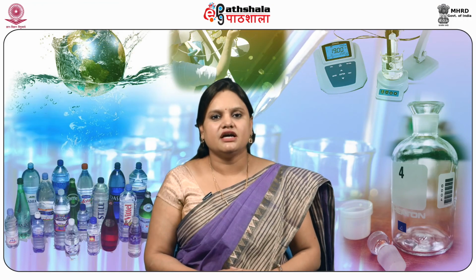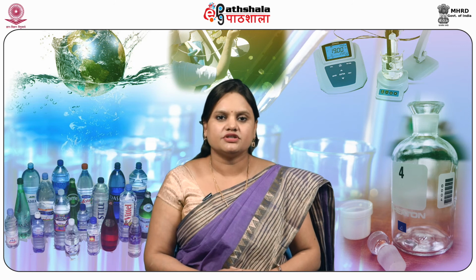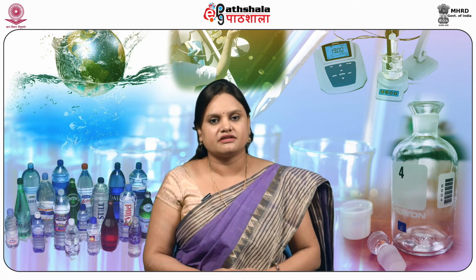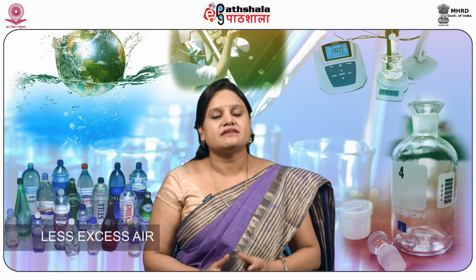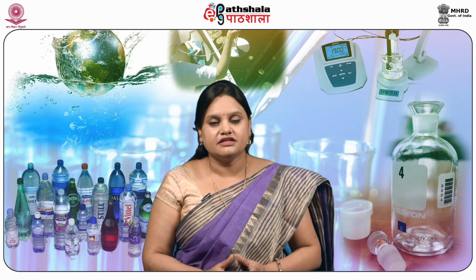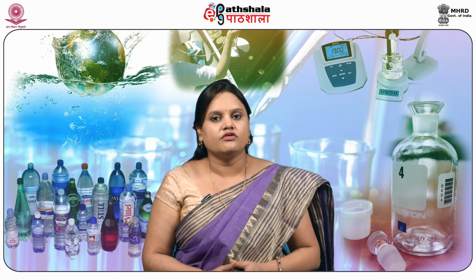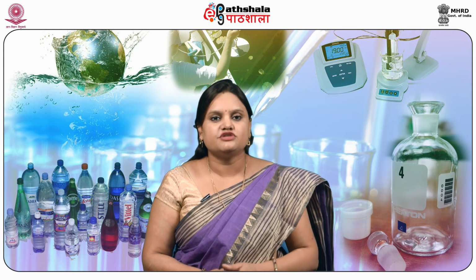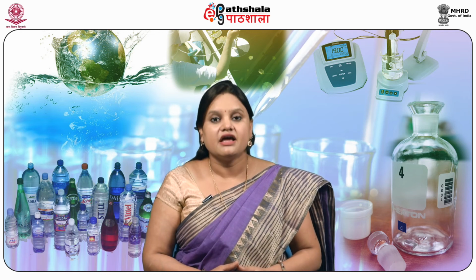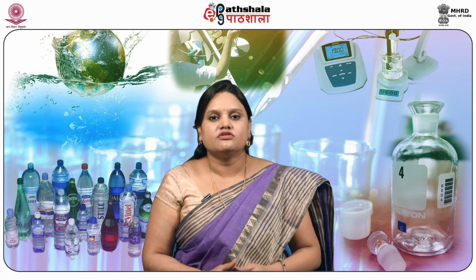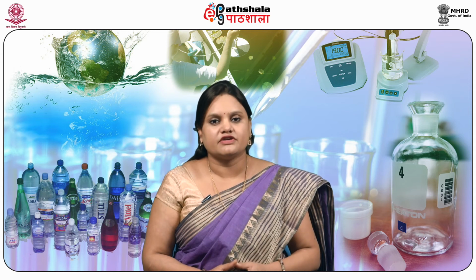Here we are discussing the external combustion pollution prevention methods. Number one is less excess air. In this method, the excess airflow for the combustion has been correlated to the amount of NOx generated. Then the second method is known as burner out of service.